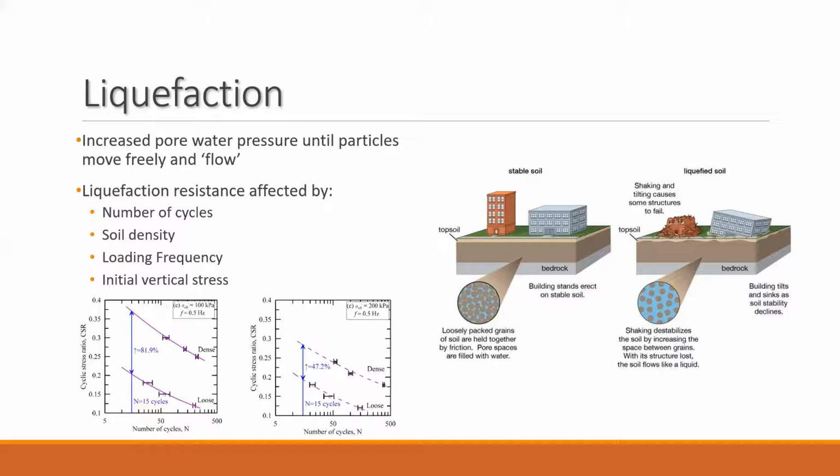An important factor that has been noticed is the soil liquefaction resistance, a value that is affected by the number of loading cycles, the density of the soil, and loading frequency. As the loading frequency increased, the cyclic stress ratio difference between loose and dense sands increased up to 82%. It was also noticed that liquefaction was reached after a larger number of cycles for a higher loading frequency.